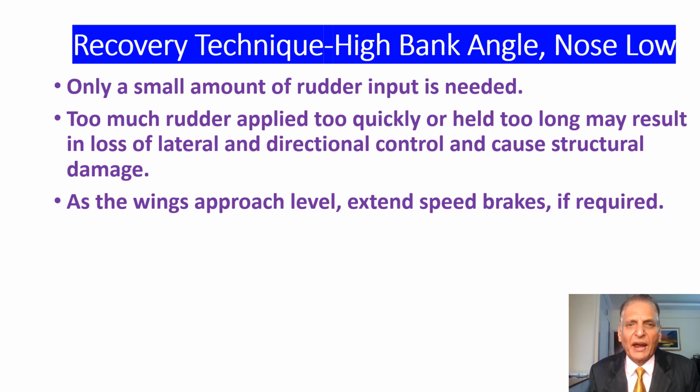Too much rudder applied too quickly or held too long may result in loss of lateral and directional control and cause structural damage. As the wings approach level, extend speed brakes if required.